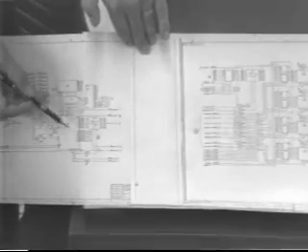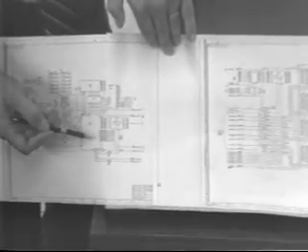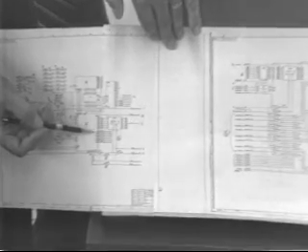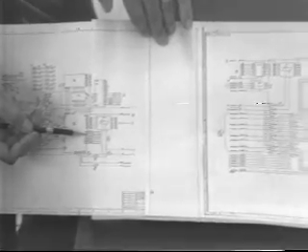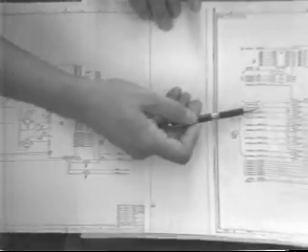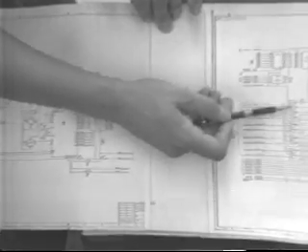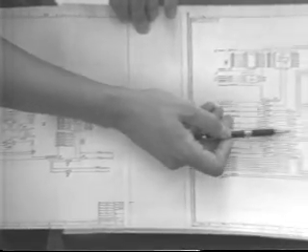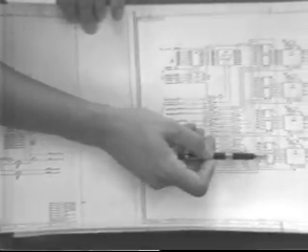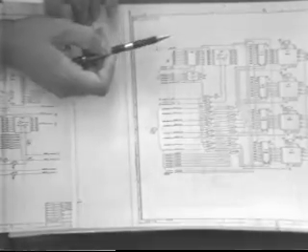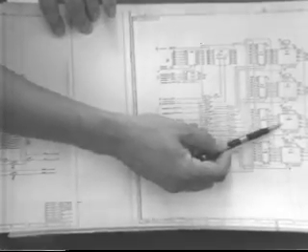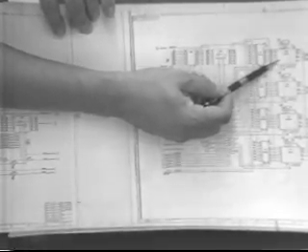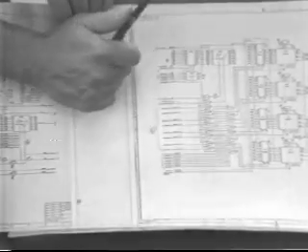So you can see that from the microprocessor on page 2, we have our ports for our LBus enable read and write, output enable and write enable, going to these lines here, through the OR gates, and enabling each RAM depending on the condition we are trying to achieve. Also, we have to enable the digital to analog converters on the right hand side of sheet number 3. Can you see that?